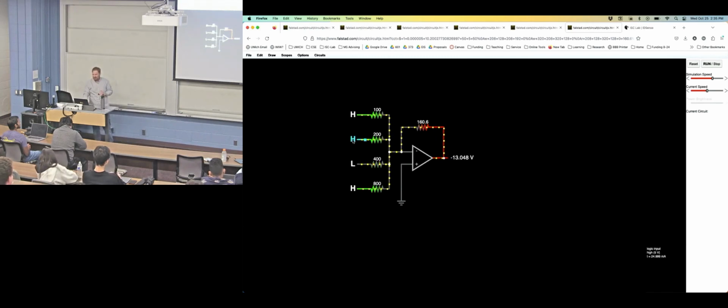So what would be one of the challenges from a manufacturing capability for this circuit? Yeah. It's true. You need at least a resistor for every bit, and you need one extra because of the summing amplifier, but it's better than the, what do we call it, the ladder version of the DAC. So we've improved in the number of switches we need essentially, and we've improved in the number of resistors we need. What other manufacturability things should we think about?